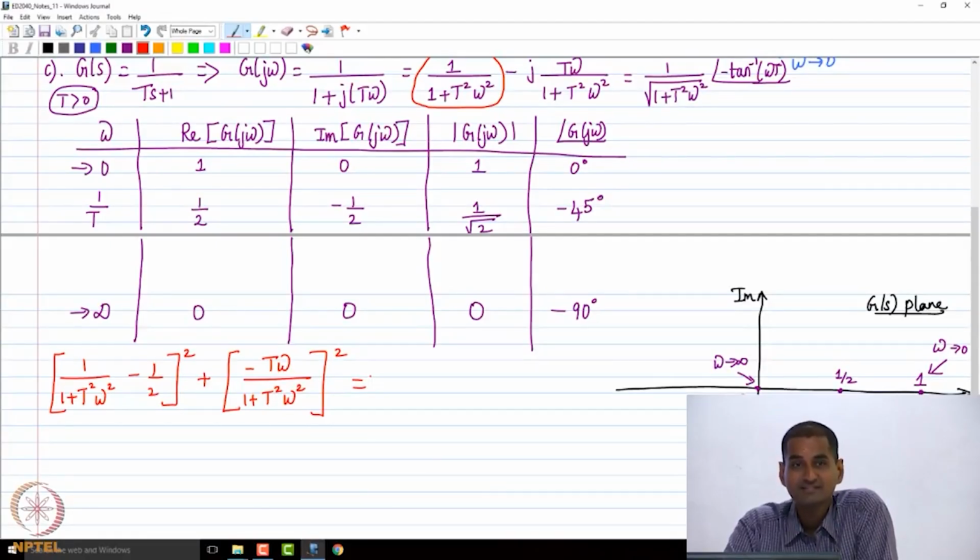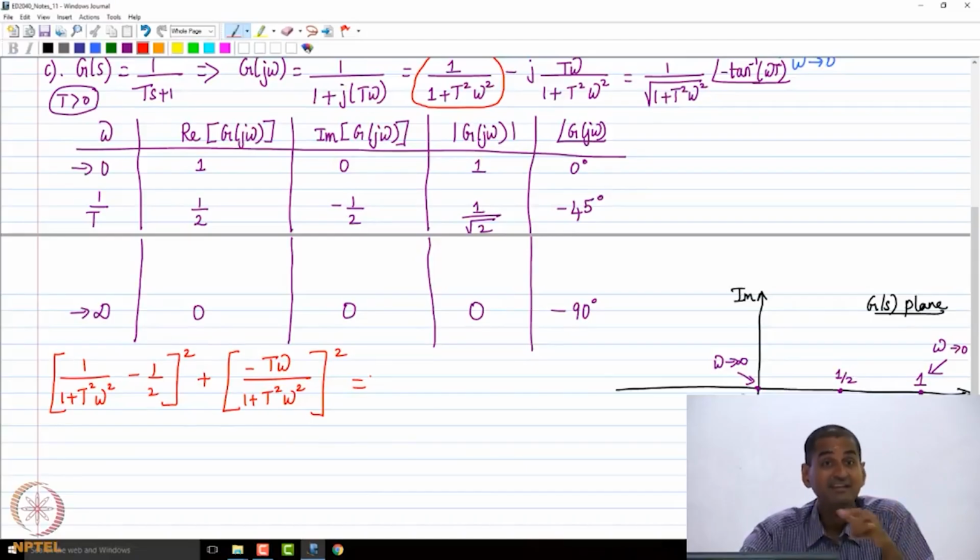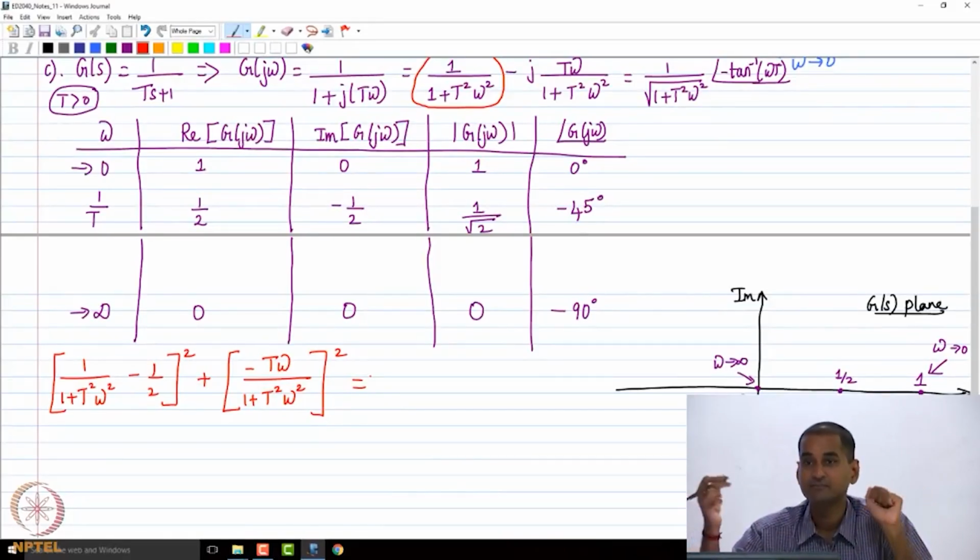See, what you are saying is that the imaginary part is minus t omega times the real part. If you take the real part on the abscissa and the imaginary part on the ordinate, you will essentially get a series of straight lines for a family of omega. But then we are not varying the real part. The real part is not the independent parameter here, omega is. So, for a given omega, the real part is not under our control, we get what it is. Is it clear?